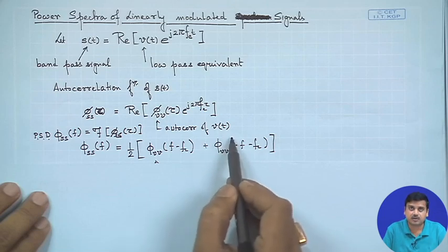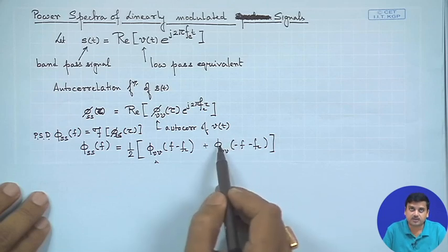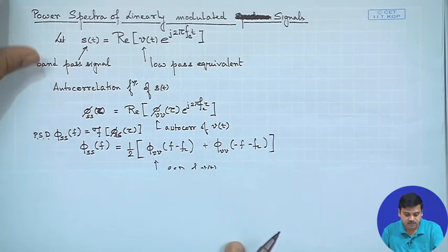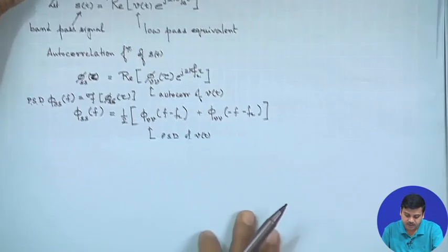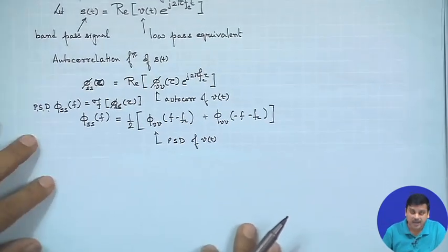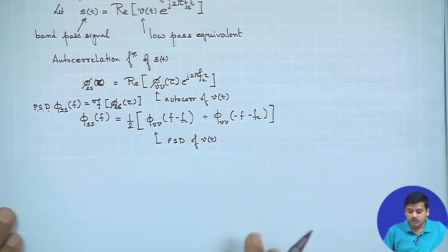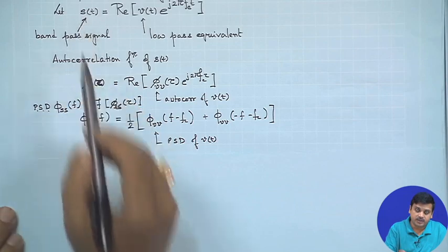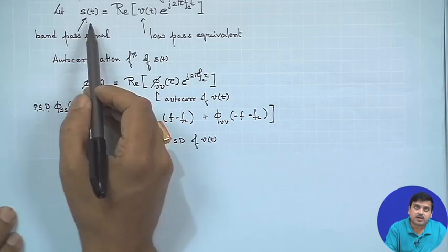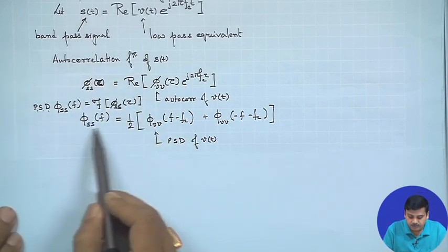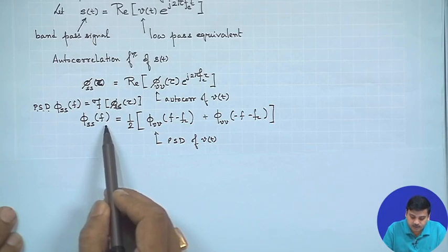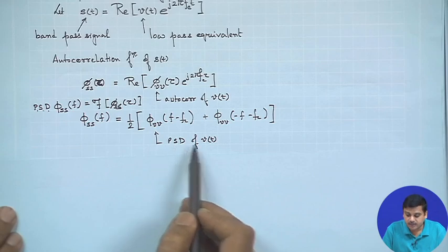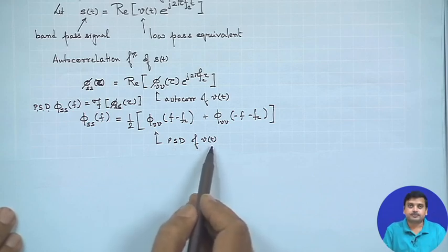Generally there is this complex representation. For certain cases we did find that we do not need the complex representation. So, of course, what we have in this expression we had before, only thing is we are using the notations which are related to the signals. Since the signals are now random signals, we have the pass band spectral properties connected to the power spectral density of the low pass equivalent process.